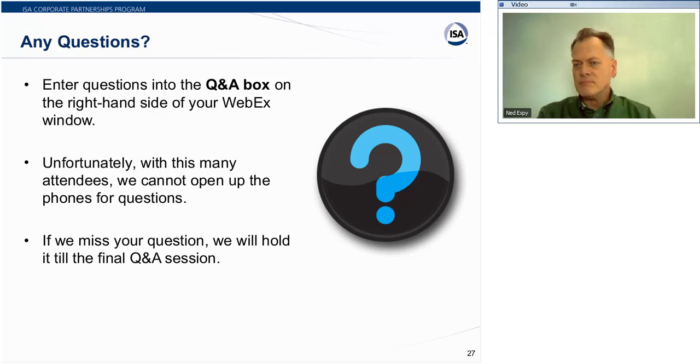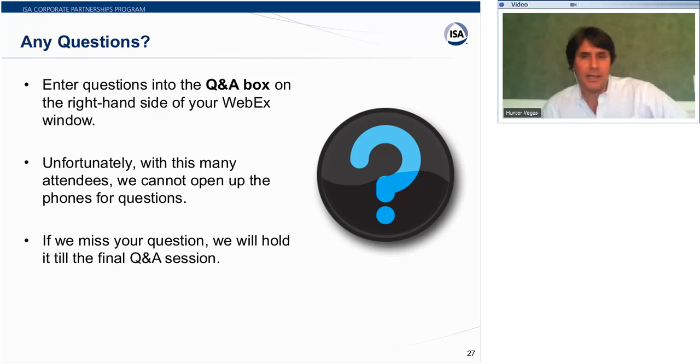All right, thanks, Ned. Next question is, I just do not understand fully the physical meaning of steam trace. Would you please elaborate? Thanks. All right, guys, I'll get that one. If you're using the regular differential pressure transmitter on the boiler drum, you can have 2 connections on the drum, one at the low level point and one at generally the high level point, and you're going to run tubing down to your transmitter. That water is just sitting there, and so it is not going to be very warm. It'll be warm within a foot or so of the drum, but once you get more than about a foot away, usually the temperature will fall off, and so it will drop to ambient temperature.